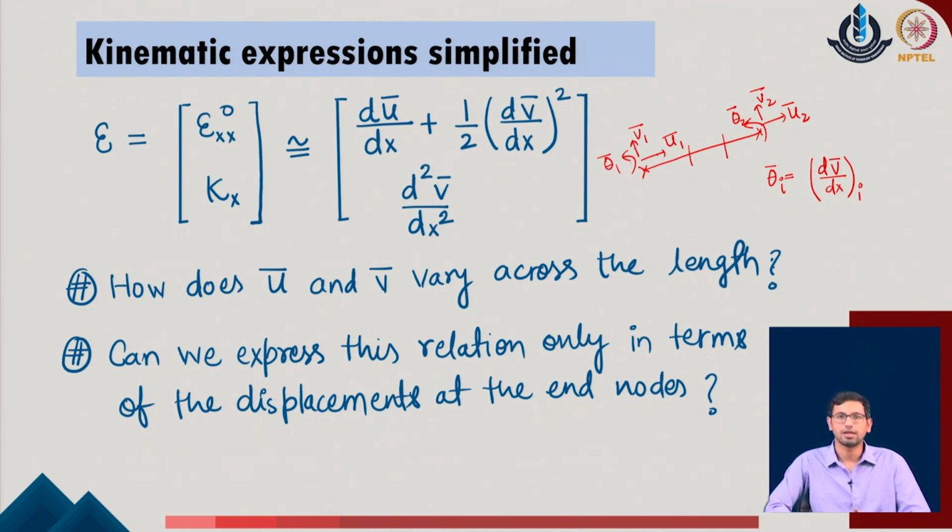So, with this idea, now we realize that we need to express our strain expressions which are defined as a function of x in terms of a parameter where the displacements are not defined by the continuous function field, but rather with respect to the standard nodal values of the given system.